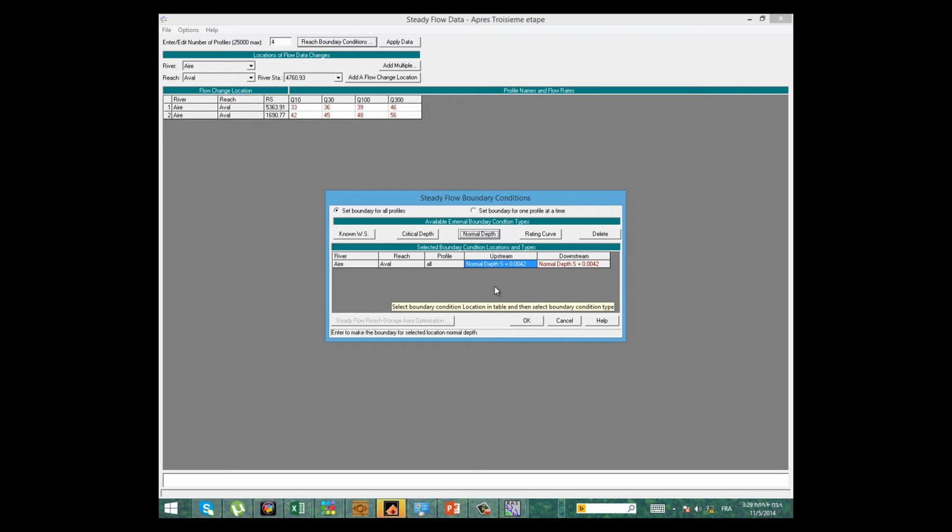You see, in a natural river, most rivers have a very low slope value, because natural rivers are always striving to become stable. It means they keep themselves in a balanced state. For example, if the water flows into an area with a very wide surface area, then the flow decreases and the velocity decreases.